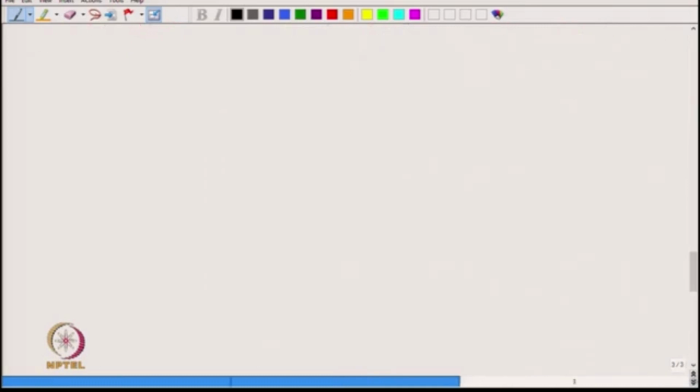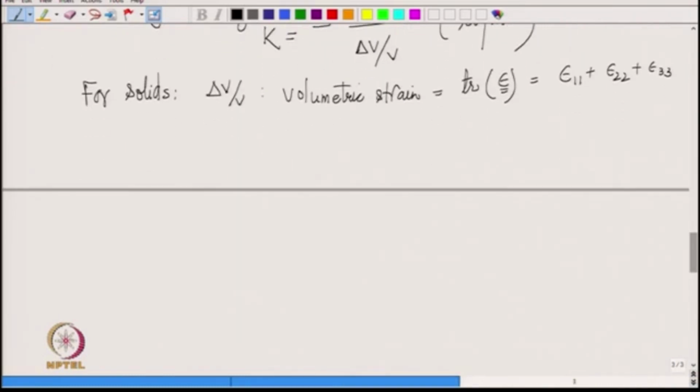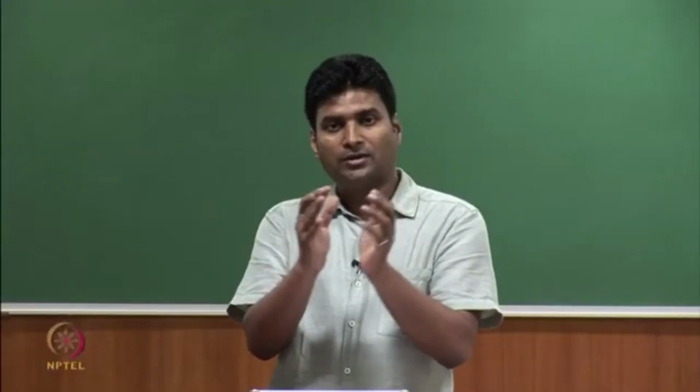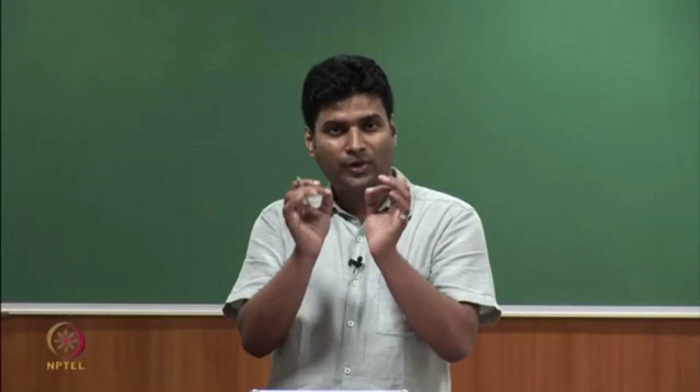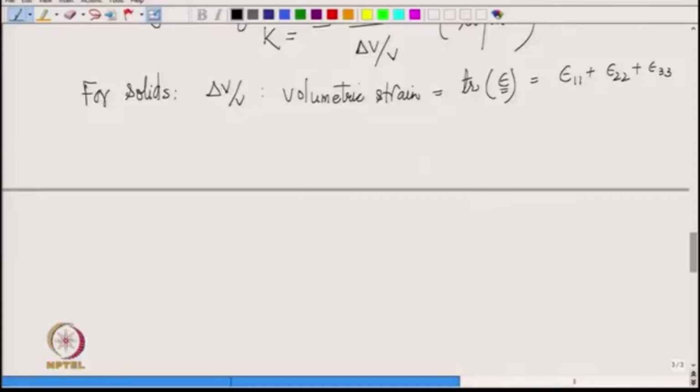So, you would recall that we had decomposed the stress in solids as a sum of what is called the hydrostatic state of stress and the deviatoric stress, and it is the hydrostatic state of stress which has direct relation to stress in liquids, right, where you only have pressure acting. So, can you recall what was the formula?